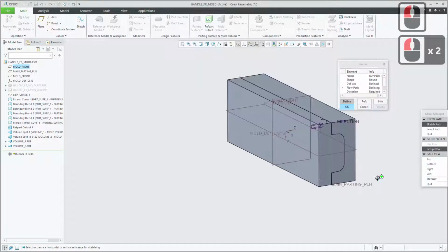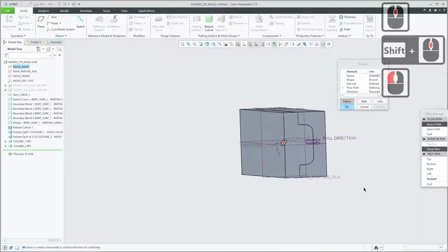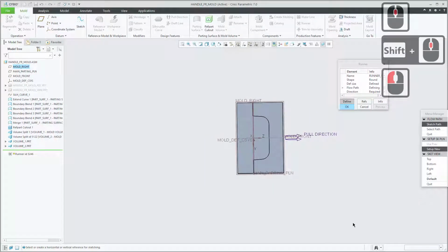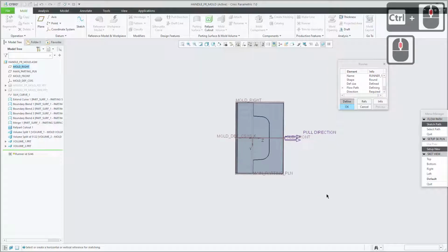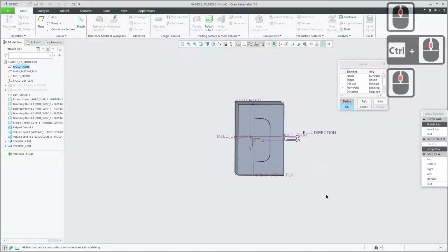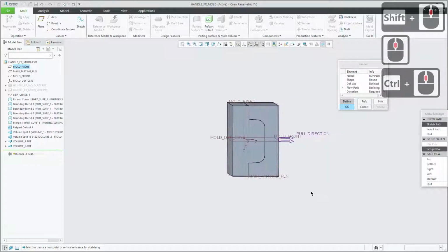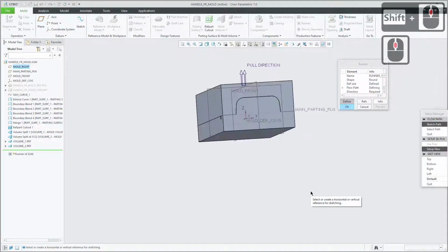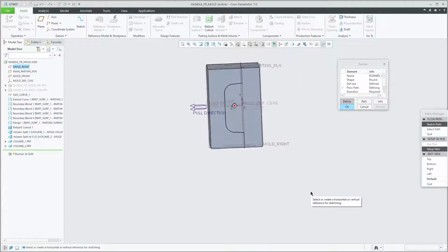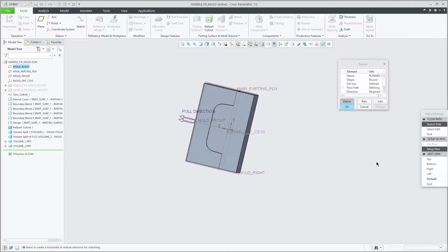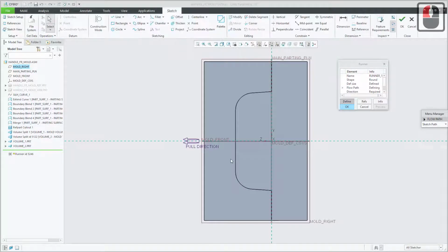Then it's saying how do you want your sketch view oriented? So just to illustrate what it means by that. So this would be one orientation. I know which direction I'm looking at the plane from. I'll see if I can rotate my view here. Easier said than done. So that would be another orientation. So it's essentially defining what direction am I going to class as up on this sketching plane. So I don't really mind, so I think I'll just leave it as the default. I don't really want to play around with that too much, so I'll just say default direction please.